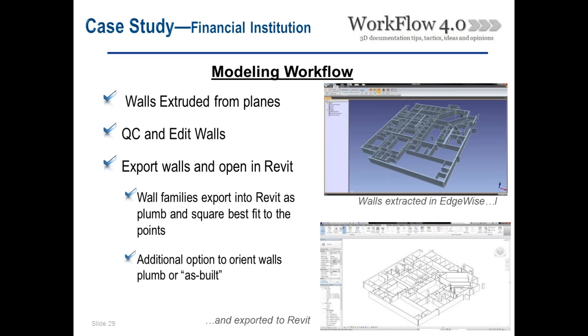Now at this stage, you'll have an option to change a few things. In particular, it gives you, before the walls are brought into the Revit project, you can select a tolerance. For this project, we selected an 1/8" tolerance, but it's important to stay within the Revit units here, otherwise it's not going to be successful. And then the end result is the lower image there, where the walls are brought in inside the Revit project. And again, those are generic Revit wall families.